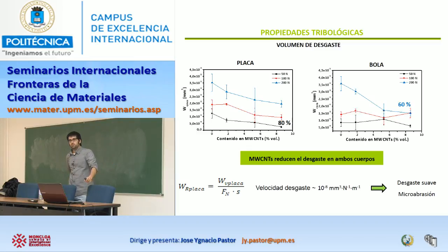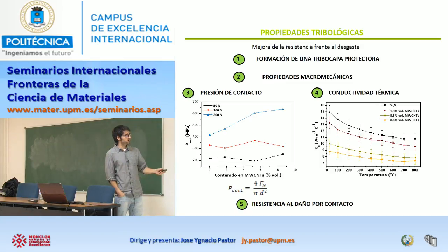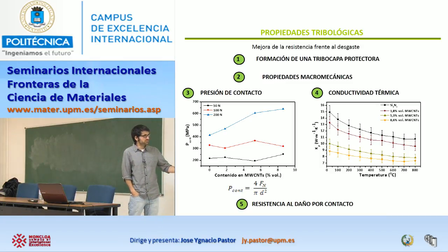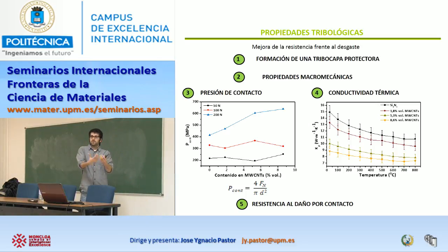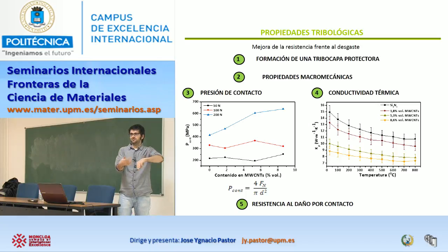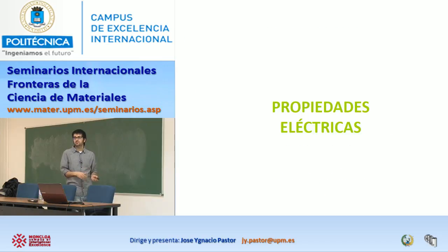8.0 volume percent of nanotubes is quite high. Even if you can do it, because for other methods we incorporate up to 20 volume percent, really well dispersed, there are different properties. For example, in that case, the thermal conductivity has no effect. Once you are past the limit, you can increase the second phase, but your properties will not really be affected. It can even go in the other direction, because then you have maybe a nanotube matrix with silicon nitride inside. You should take care of that, but of course you can incorporate until you see your thermal properties change; it depends on the property.